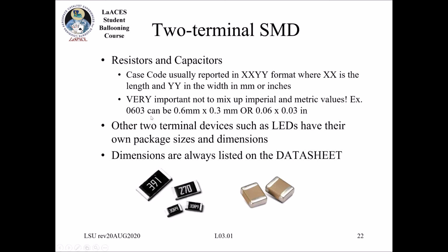And then again, you can see that there is at least some writing on these. This might be a standard with resistors. Typically, I know from a data sheet, and you can see the capacitors are just, we have no idea what values those are. And again, keep the packaging with the part, so that way you know what it is and you can go find out exactly what that value is. Hopefully it's printed on the package.